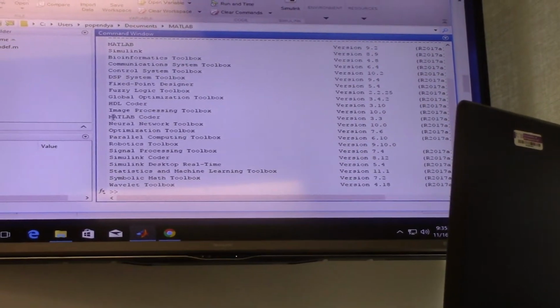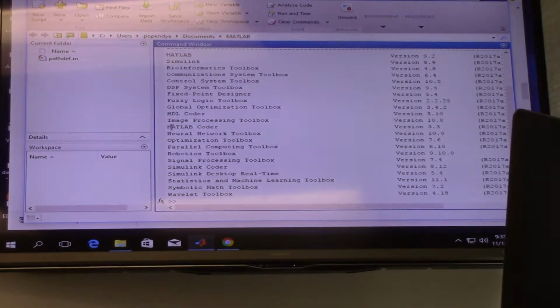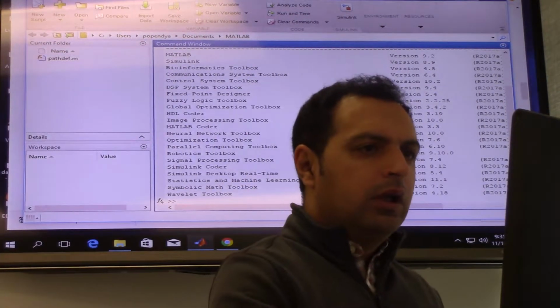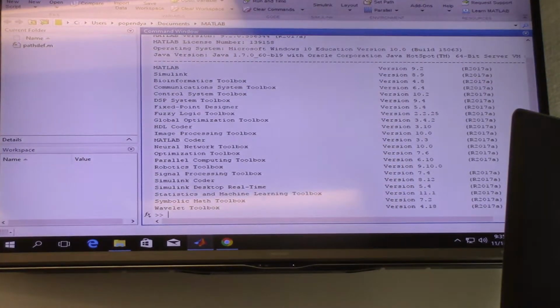I'm going to have you do a program for one joint, and I expect you to apply that for the n joints. So first we'll do a cubic polynomial, and then I'll give you a sheet so that you can extend that to a quintic polynomial. So first we'll do q of t. This is your cubic trajectory.